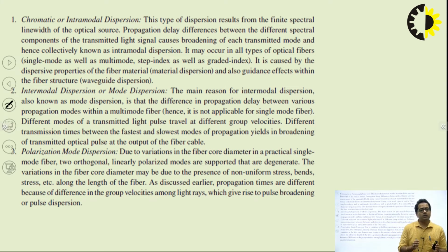Why? Because in a single mode fiber, intramodal dispersion basically surpasses the other kinds of dispersion. So in a single mode fiber, intramodal dispersion will be there, and in a multimode fiber we have intermodal dispersion, which is because of the difference in propagation delay between various propagation modes, and it occurs inside the multimode fiber.